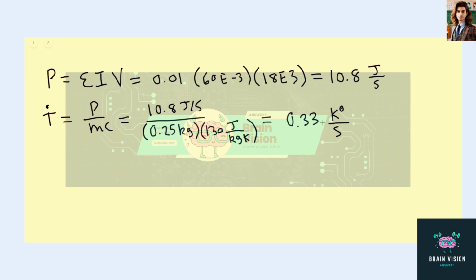So we want to maximize M and maximize specific heat. We could take a look at a table listing specific heats and mass per unit volume. One that jumped out at me that has a very high specific heat is concrete, which in addition to being pretty massive and having a high specific heat is also relatively inexpensive. It doesn't have to be a very exotic material. So perhaps this would be an interesting material to use.